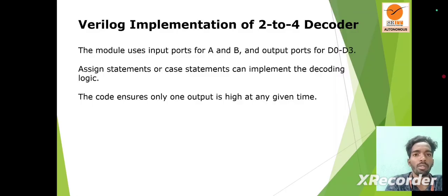The module uses input ports for A and B and output ports for D0 to D3. Assign statements or case statements can implement the decoding logic.